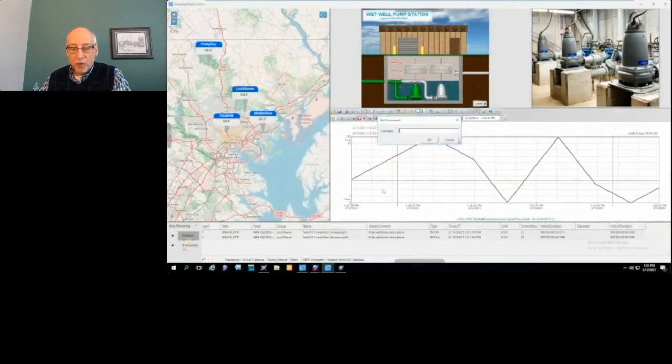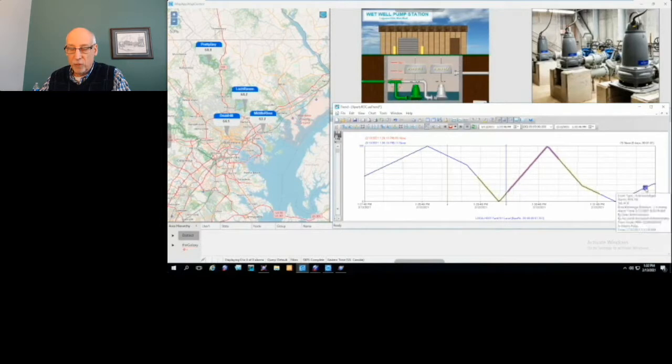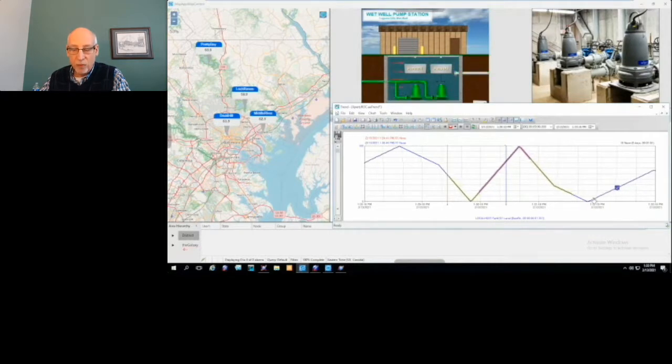Also, one of the things that we have now with storing our alarms in our historical database, we can store things like when an operator acknowledges alarms, and we overlay the alarm information on top of a trend. So you can see on the trend chart there that the alarm indeed was acknowledged, and that shows up on the actual trend control. So some nice new features within System Platform for alarming capabilities. I can overlay that alarm information directly on my trends. I can see when an operator acknowledged an alarm. I can see the status of alarm conditions within my trend controls. So great tool for seeing alarms within my System Platform.